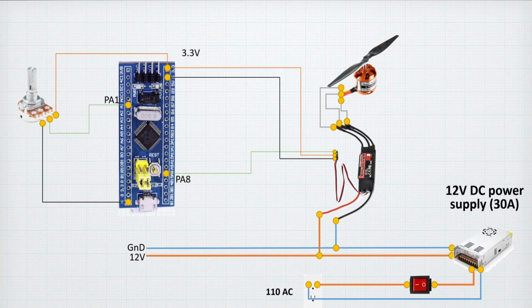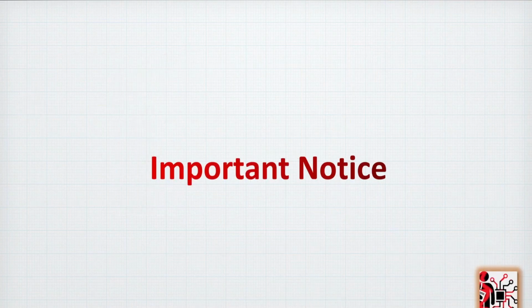And again, you don't put your whole power system on until you are sure that every connection is correct, and you have your microcontroller ready to fly and also at 0 PWM or 0% of your speed. Okay, so here comes the important notice, and this is something extremely important that I would like everyone who will be using the system to be very cautious about.